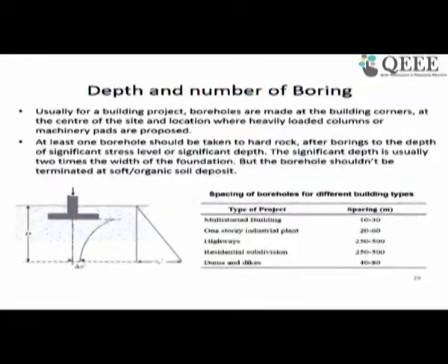Now, the depth of boring is also related to the significant depth. For a foundation, as you may know, it is roughly 2B, where B is the width of the foundation. So that would be the significant depth, and your borehole should go beyond that.